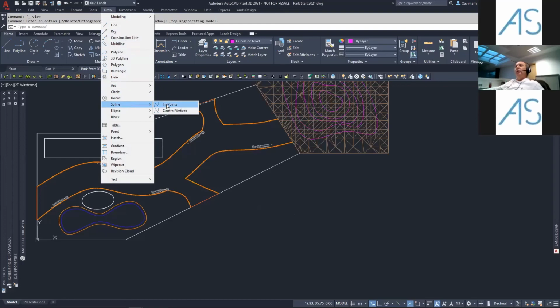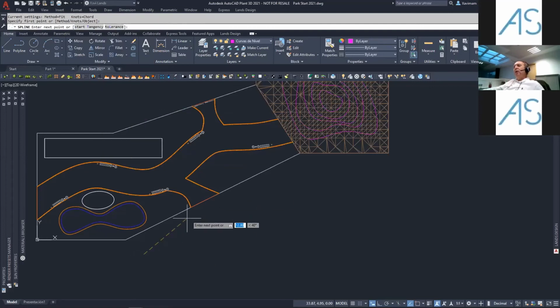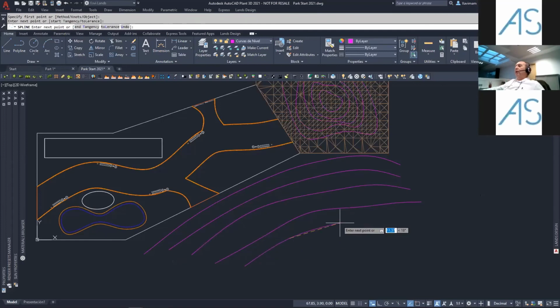I can create some splines to create these curves. Of course, we can use a polyline too, and afterwards edit this polyline to create the splines. But I'm going to create the splines directly in this area. In this case, the splines are going to more or less follow this contour. If I place 4 or 5 lines and I place a meter, there's going to be 4 or 5 meters of height information too.